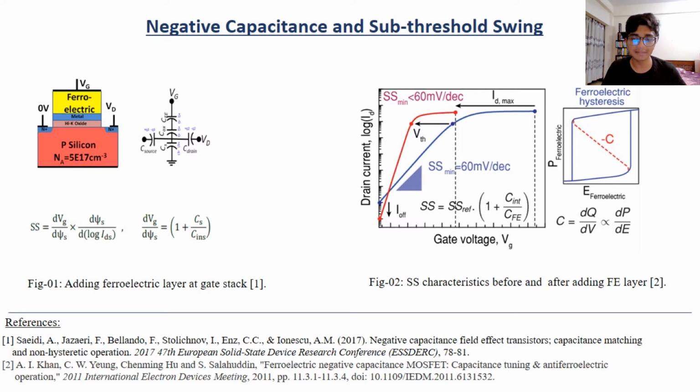It is theoretically demonstrated in figure 1 that a ferroelectric insulator such as aluminum hafnium oxide operating in the negative capacitance region could act as a step-up transformer of the surface potential in a metal oxide semiconductor structure, opening a new way for the realization of transistors with stable subthreshold characteristics of less than 60 millivolt per decade without changing the basic physics of the FET.